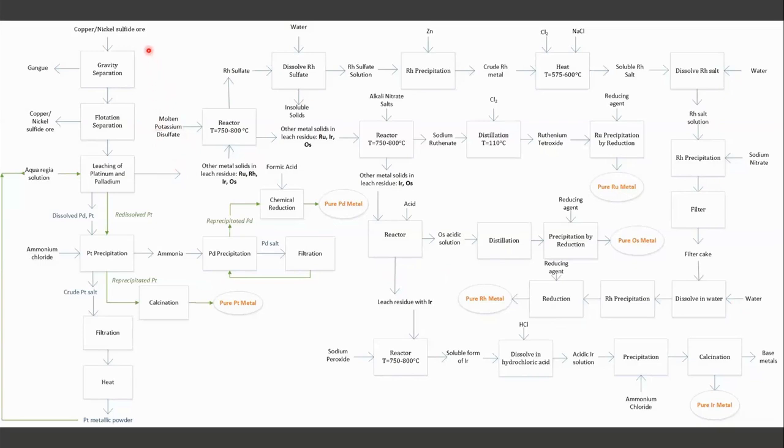In this instance, we have a nickel and copper sulfide mine. This is very similar to the process run within Nornickel and similarly in parts of South Africa, where you'll essentially have your material. You'll have to refine this, so this will go through a process. The gangue is what has been termed pre-slag, for anyone that knows metallurgy. Slag is the stuff that when you melt metal, you skim off the top and it's essentially wasted product. The pre-slag is the stuff you don't even want to bother melting. You want to just get rid of that because that just adds cost.